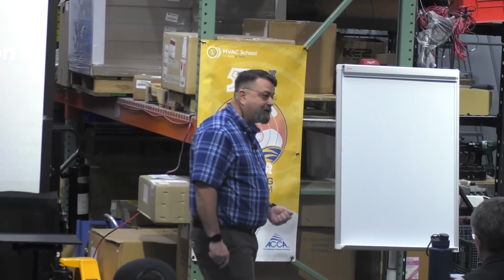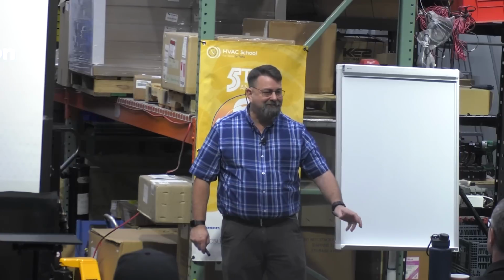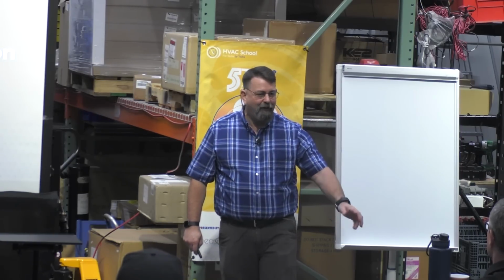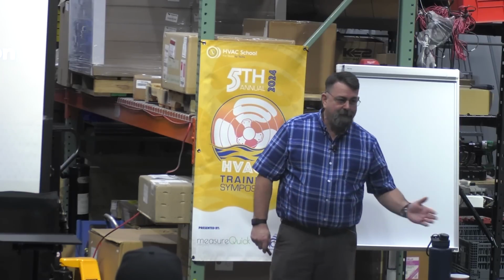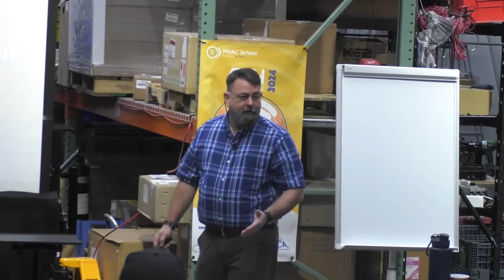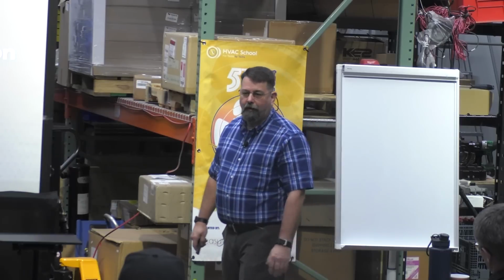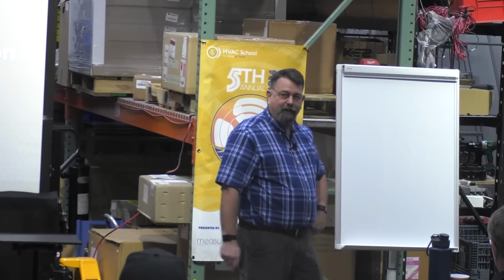That's pretty much what it comes down to. So for serviceability, that may not be a refrigeration tech, right? Most of the time it's not a refrigeration tech. We're going to give them a garden hose handle. They recognize it, they know how it works, right? They just turn that handle all the way off. They call their monitoring company or whoever that might be and say, hey, don't call out an alarm on this thing. I'm going to hit it with some hot water, right? Then they unplug their fans so there's no power. They have no refrigeration, no power. They hit it with a hose. When they're all done, they plug their fans back in. They open their garden hose up, right? Turn the liquid refrigerant back onto the TXV. Yeah. Another very good practical question.